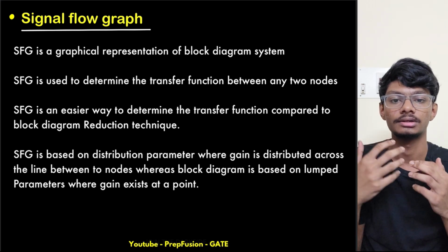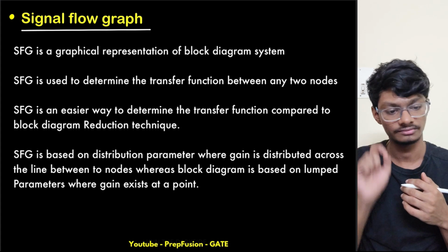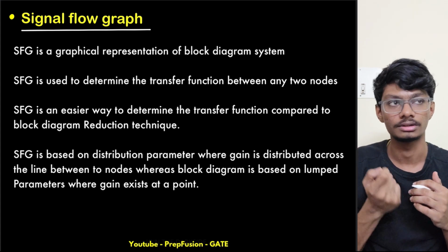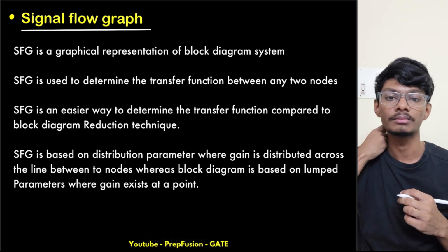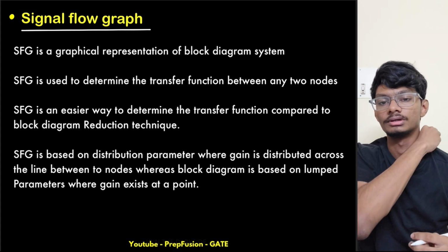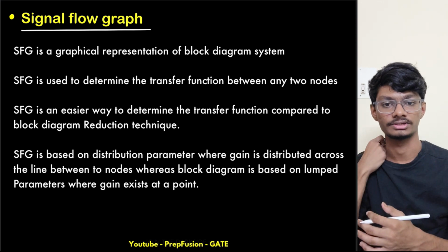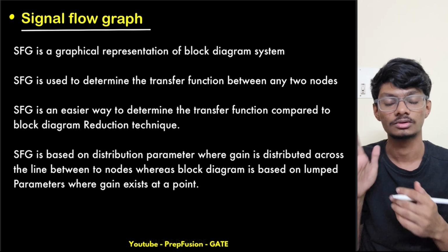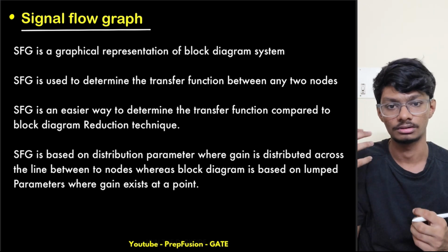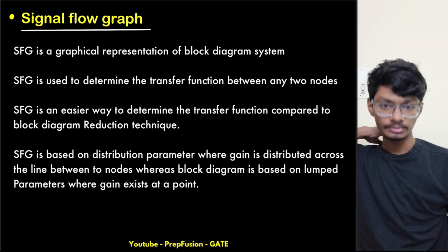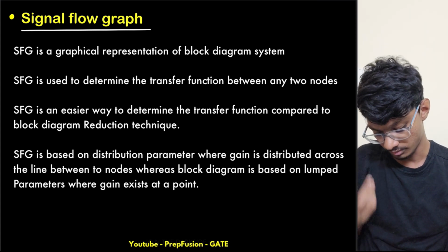To understand it in an easier manner, analyze it in an easier manner, but to further simplify it and calculate the whole transfer function, right? Calculating the transfer function from the block diagram may become tedious sometimes. As you saw, as I was solving that question at the start of this lecture, it was becoming tedious. So using SFG, we have a particular formula. If you use that formula, we'll get our transfer function, right? So that's why it becomes a bit easier. Okay, so these points we have already understood.